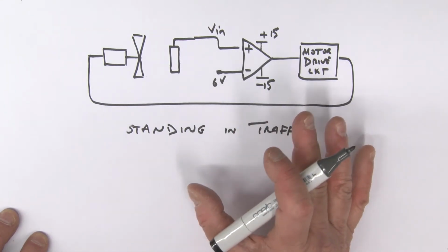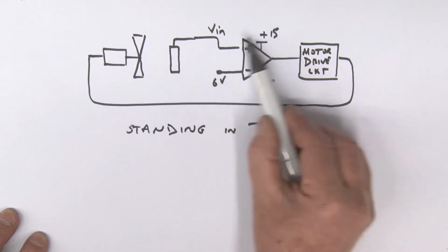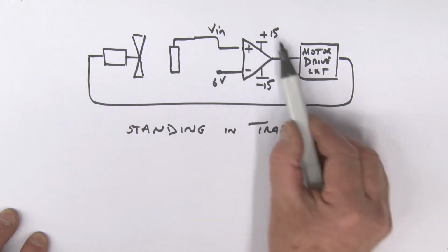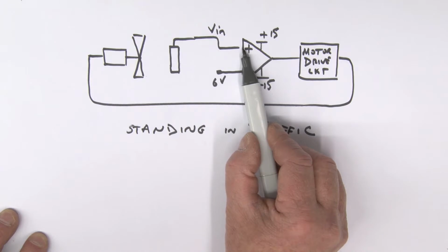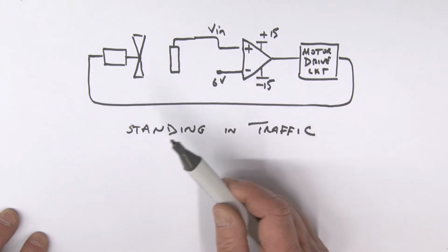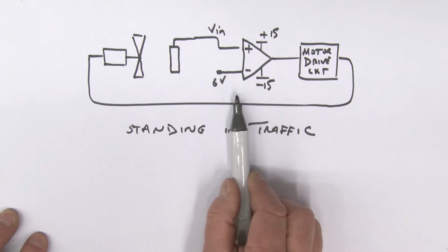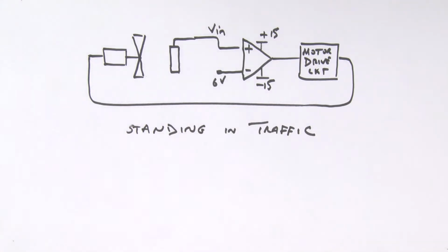So we really want a better system than this. This is simple, but we might need to add a degree of complexity: we have a turn-on voltage, let's say that is 6 volts, but we have a turn-off voltage which is less than 6 volts, maybe 4 volts or something of that sort. So we need to think about how we might design a circuit to actually do that.